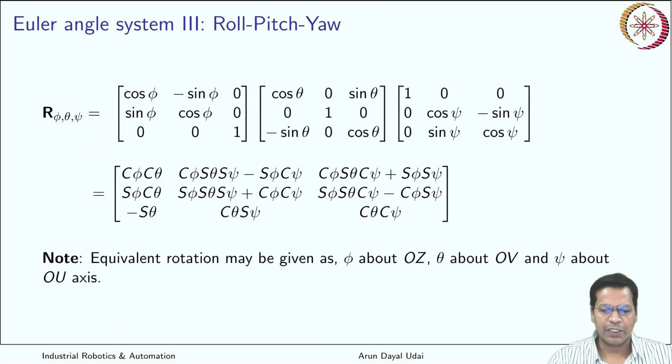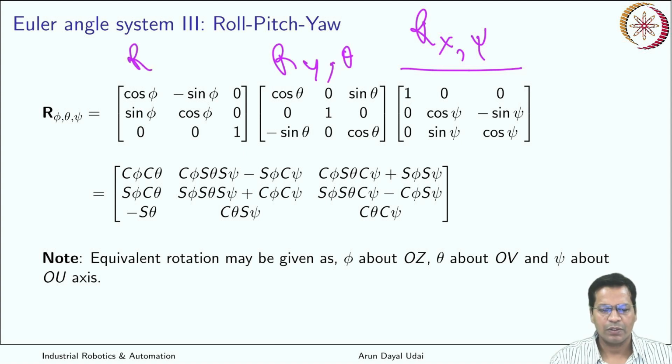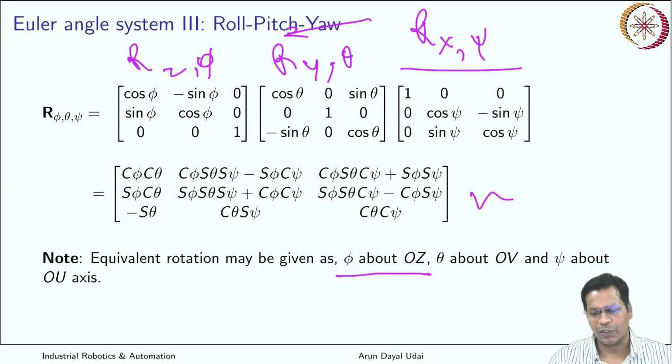So simply this can be expressed like this. This was the first operation, rotation about x, rotation about y, rotation about z. So these 3 rotations, 3 multiplied, and you arrive at this. Now again, can it be inverted back to a relative frame of reference? Yes, it can be. So this is your first rotation. This is rotation about z-axis. Then you do post multiplication by this.